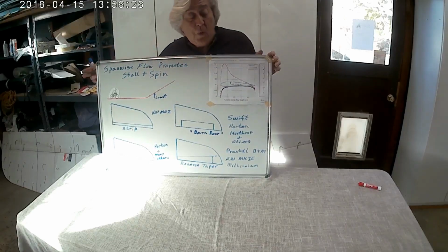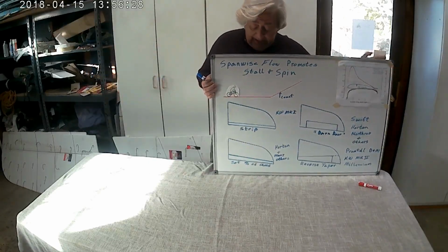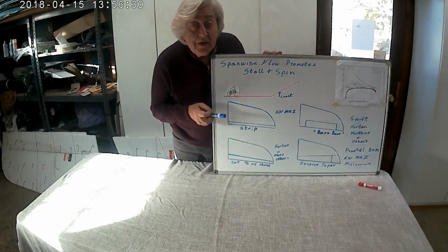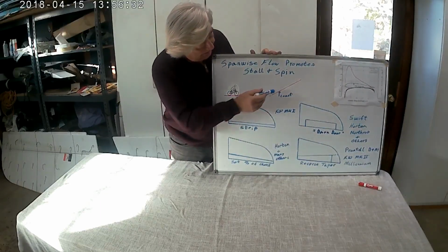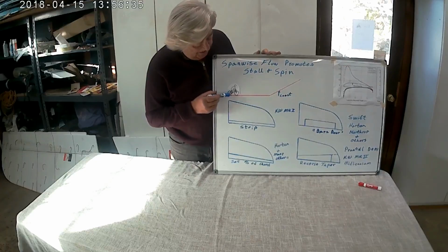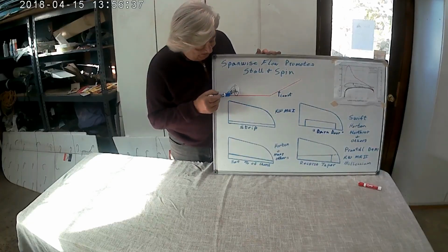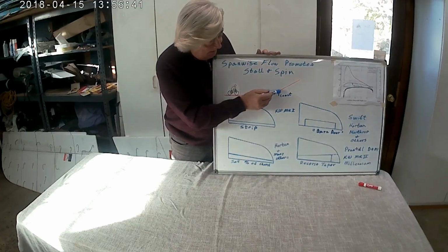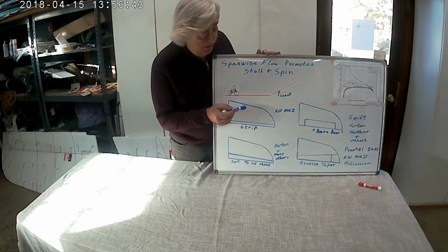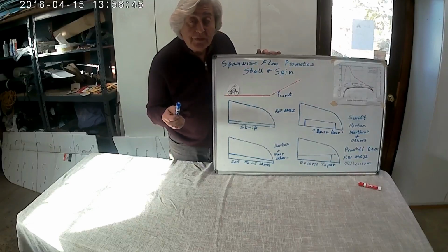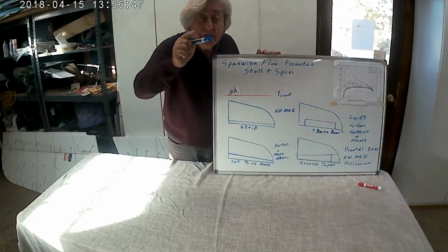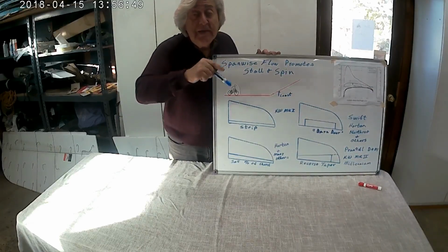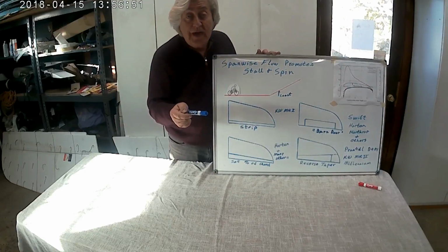And what you can equate this to, I'll do a cheap analogy here, of a guy on a bicycle trying to get up a hill. Now, we made it a rule in his little race that he can pedal as hard as he wants, he goes as fast as he wants until he gets to here, and then he has to coast. Because that's what's happening on the airflow. That flow is accelerating, accelerating, accelerating until you get to the maximum thickness point of the airfoil, and then it has to begin to slow down.